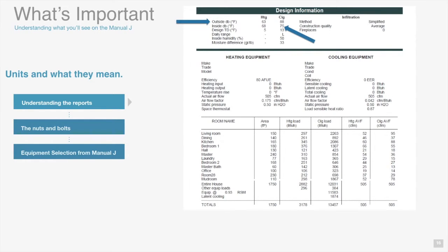If that number goes up towards 80, you're going to have a smaller air conditioner. If you move that number down to 72 or 70, you're going to have a much bigger air conditioning unit, and the unit that you'll have to specify to cover the load will get bigger faster as that number goes down. It won't move as much if that temperature goes up, but it will move some.